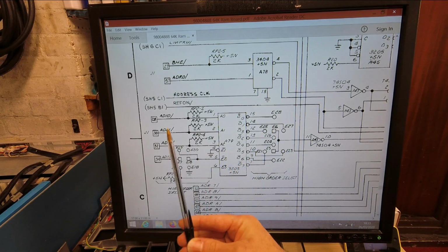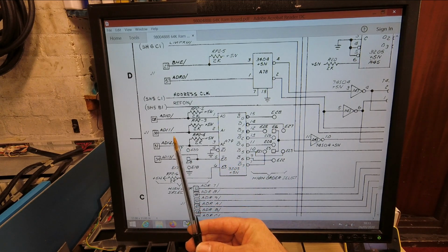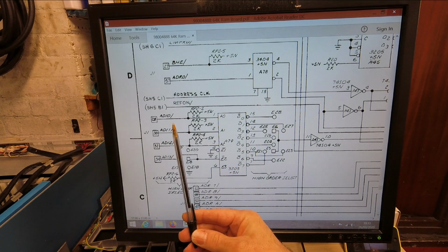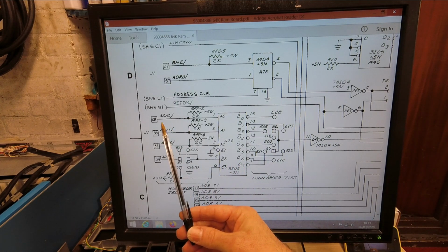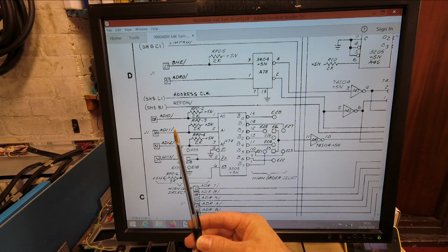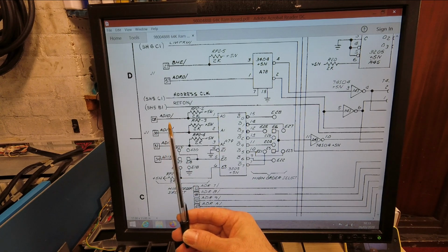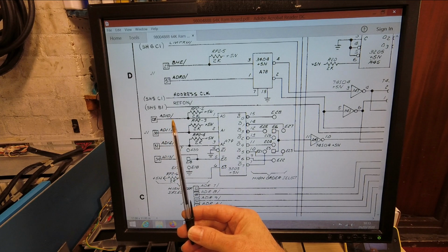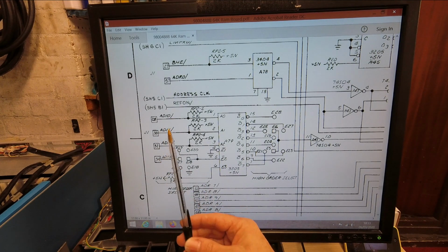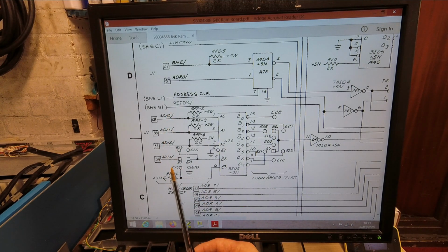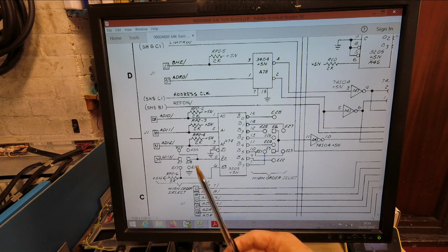Right, this is the 3 to 8 line decoder I was talking about just now. You can see it's attached to the upper address lines. It's a bit confusing because Intel call address 15 ADF in hex. So AD10 I should say is the next address line up. These 10, 11, 12 and 13 go nowhere on our MDS-800 because it's only an 8-bit machine. They could potentially be used by an in-circuit emulator card, but not at this point in time.